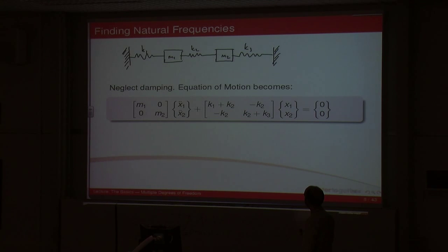That sticks in there. And then the off diagonals, you look at this one obviously is between 1 and 2. This is between 2 and 1. Well, you look at what happens. You've got the minus sum of the springs connecting mass 1 and mass 2 together. So you have obviously minus K2 here. It's symmetrical, so that's minus K2. There's your stiffness matrix. So basically, just by looking at the picture, you can come up with the equation of motion straight away. Okay, just by looking and seeing what springs and what masses are connected to each other.